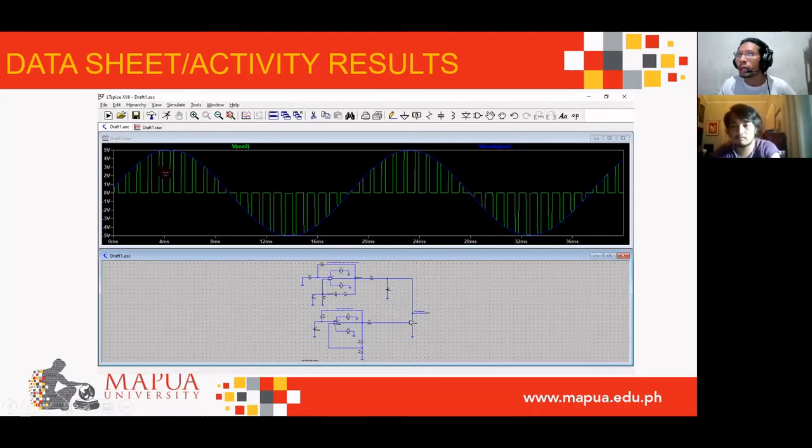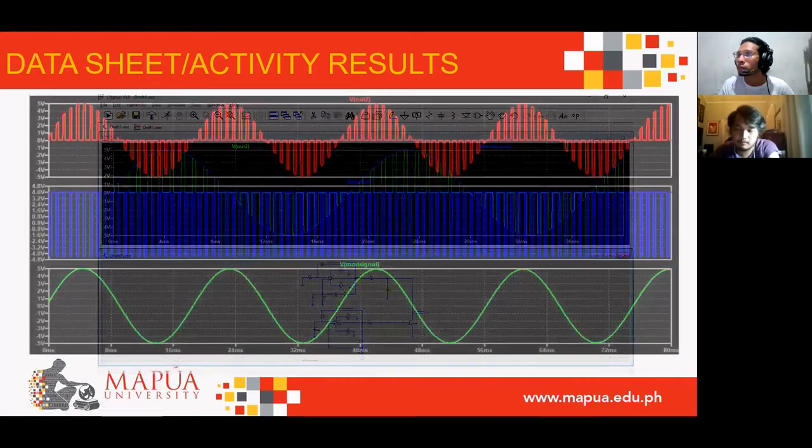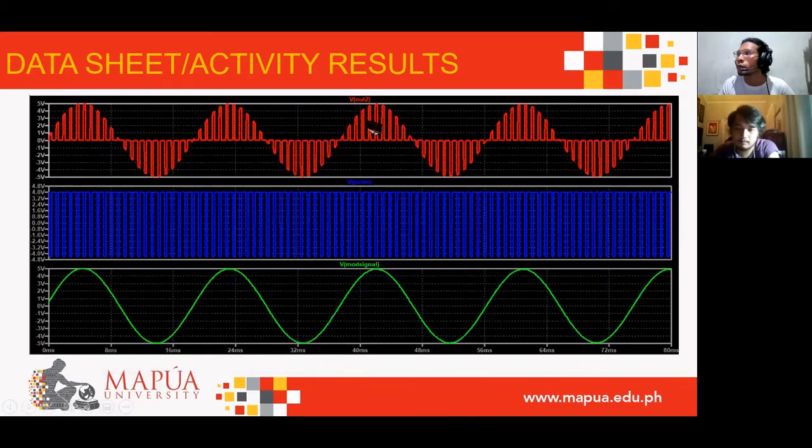So to verify that the amplitude of the modulating signal varies the carrier pulse train, we can see that the blue line, or the sinusoidal wave, envelopes the PAM signal. A narrower pulse in the green line, a narrower pulse width is observed, which means a PAM has a low duty cycle. So you can see in the figure the three outputs of the three subcircuits of the pulse amplitude modulation circuit. In summary, the PAM is the product of the modulating signal and the carrier pulse train.